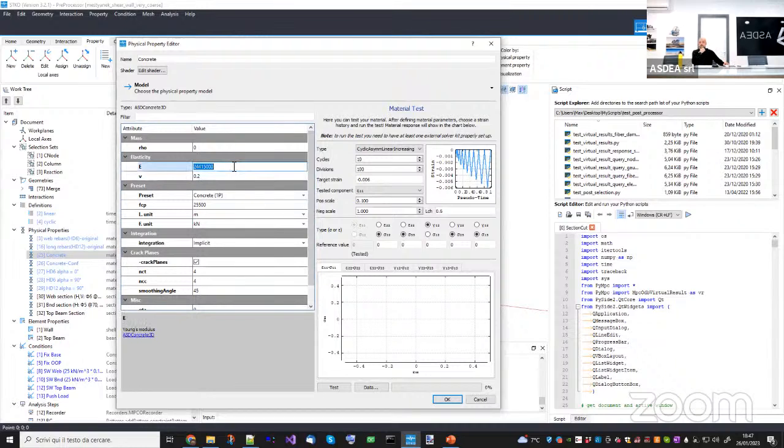I simply put the Young modulus that I have from the paper, the Poisson ratio, and then I use the preset with the 1 parameter. I was curious to see if the presets were working fine for standard concrete. So I put the value, oh, here I'm using meters and kilonewton. Okay, so that's why you have this value. It was 25.5 megapascal, basically.